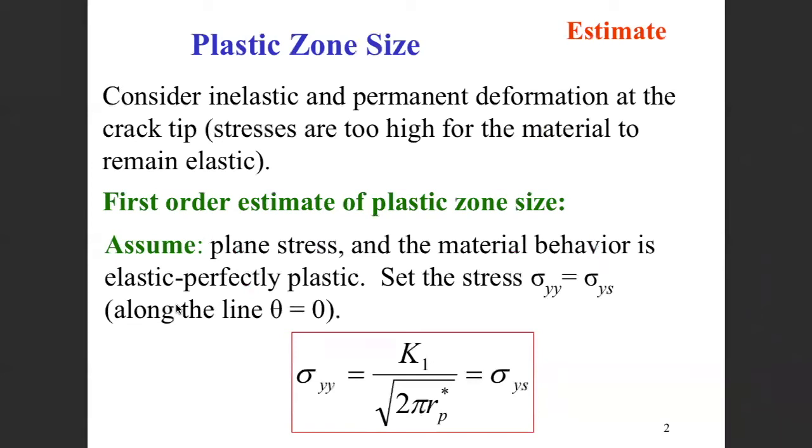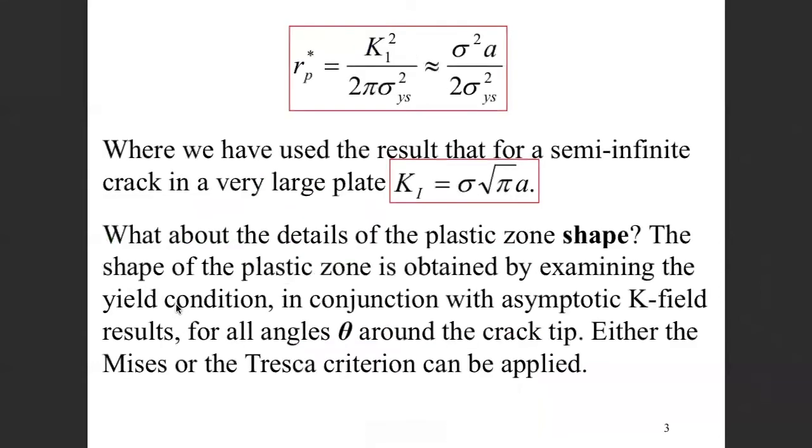And if you're doing design where the plastic strains are small, if you care about yielding, you don't want your bridge to yield, you don't want your airplane to actually yield. Most design is elastic. So if you're only experiencing small plastic strains, it's not too big of a deviation from this, and it's actually going to overpredict your plastic strain, which is good from a design point of view. So a lot of times we assume this elastic perfect plastic.